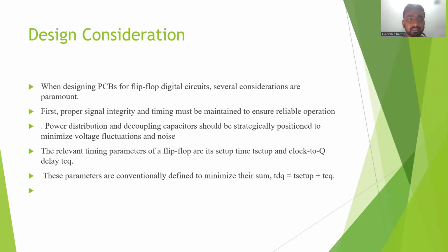Design considerations. When designing PCBs for flip-flop digital circuits, several considerations are paramount. First, proper signal integrity and timing must be maintained to ensure reliable operation. Power distribution and decoupling capacitors should be strategically positioned to minimize voltage fluctuations and noise.